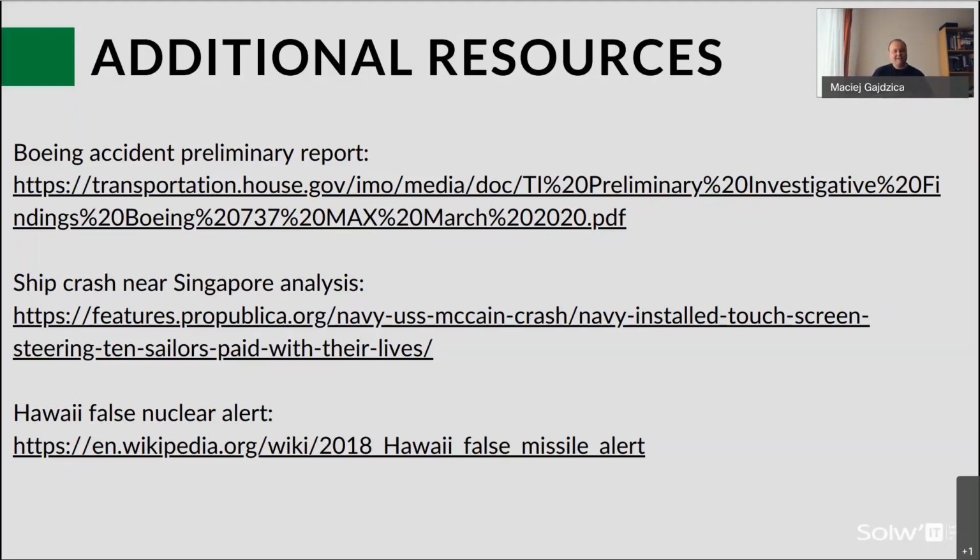And actually, the best way to avoid a situation where this safety critical system is part of the problem is to use the simplest solutions that we can. So, for example, if we can use a hardware solution or a software solution, it's better to use hardware because it's more reliable. It also fails in some probabilistic fashion that we can predict, and it doesn't have undefined behaviors. So actually the simplest solutions are preferred to make it less complex.